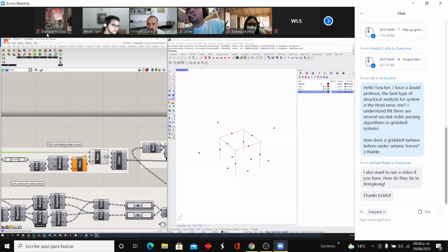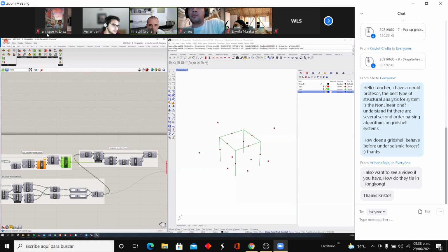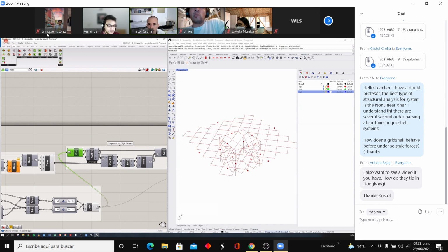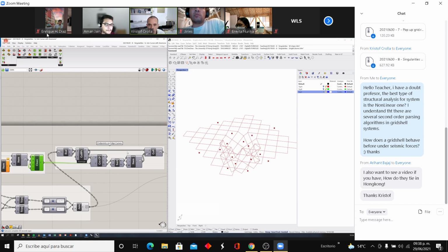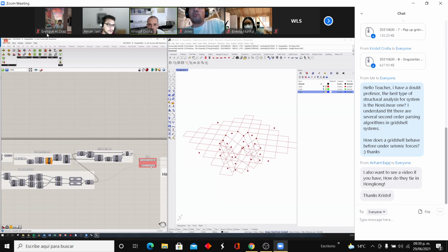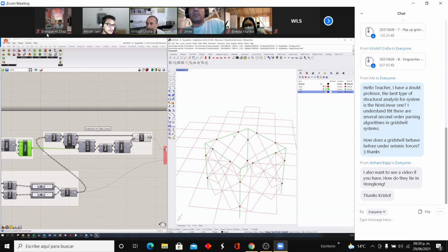That's it basically. So here now I have my clean edges only occurring once. And then I need to find the end points of all my curves that are on top of these lines. So I can find all the endpoints of my curves. I can check the distance to my curve set here. I can sort them based on distance 0, and then I can basically call out the points that I have here. So now I have found all the endpoints of my curves that are placed on top of, switch this off, that are placed on top of my joint edges. Yeah, so these are the points that I need to evaluate. And each and every one of these, I need to make the assessment on which ones to join.